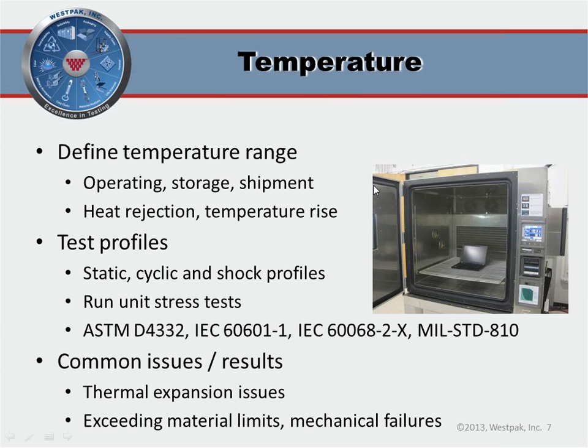So there's a couple ways you can approach this. One thing to do is think about the industry norms. For a laptop, it might be used indoors or in a mild outdoor environment. So think about what that environment is and what those temperatures would be. You can look at comparative products. A laptop's a very good example. There's lots of them out there, and see what the industry norms are for the environment.